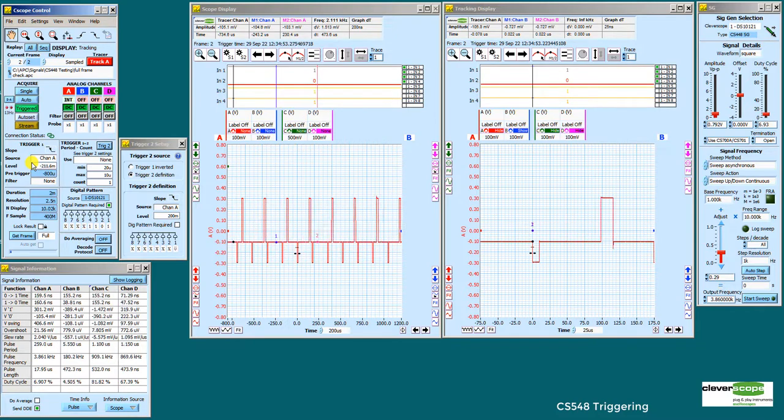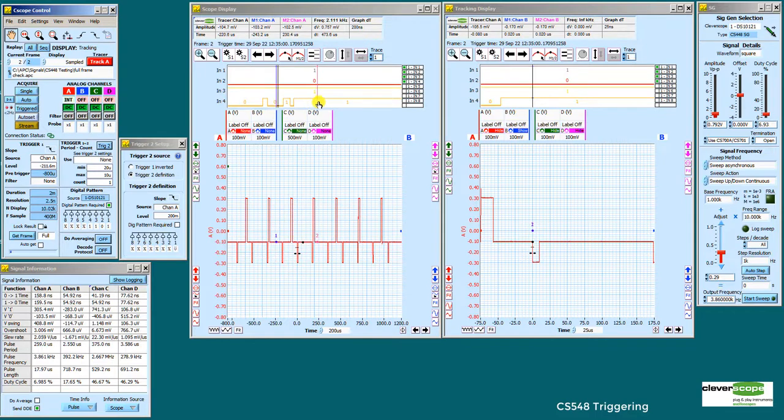There's some switch bounce in the one I'm using. You can see it switching there. If I go and set this to single and do the switch, you can see the transition there as we go from 0 to 1 on the switch. So this is useful if you have some state information and you only want to capture when the state is in a particular scenario. For example, you're looking at a digital system that's got some outputs like an SPI, for example, and you want to trigger only when the address lines are set to a value. You can make sure that you'll only trigger when these address lines match up.